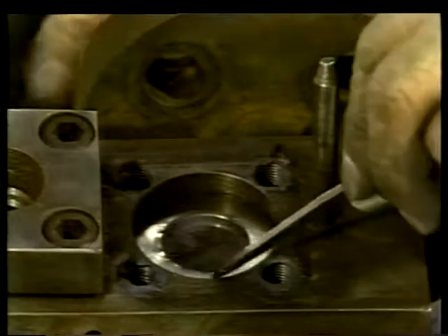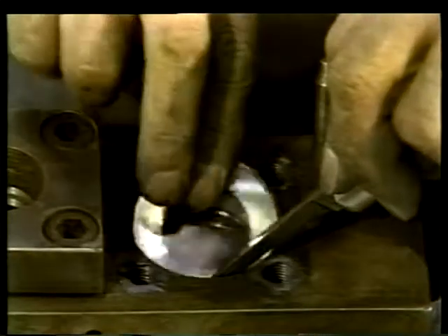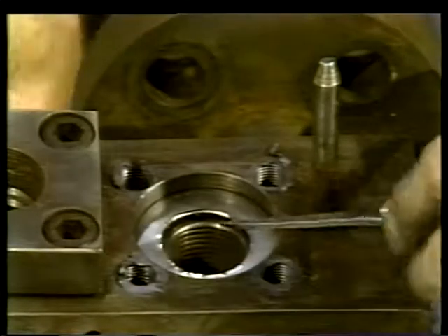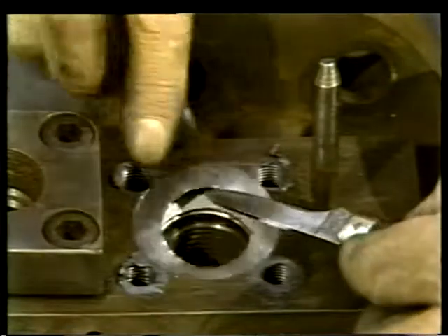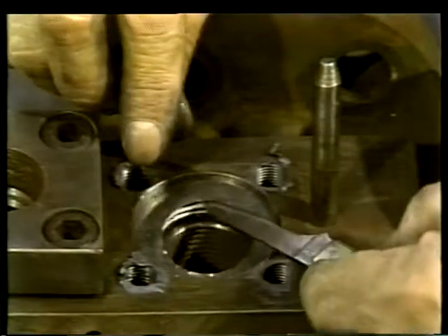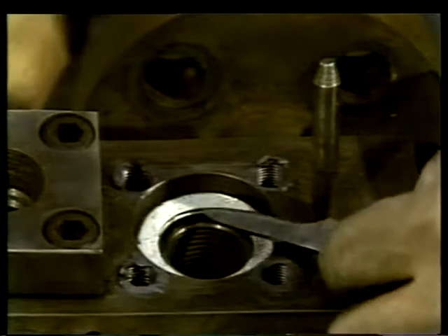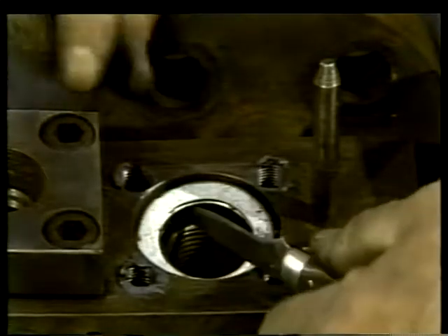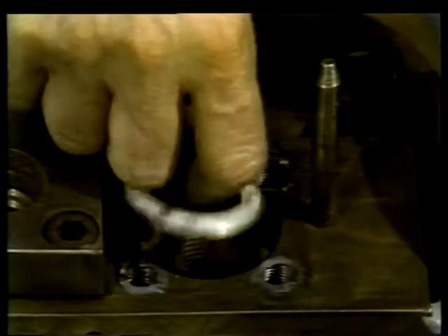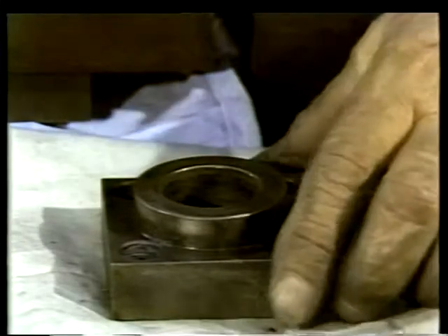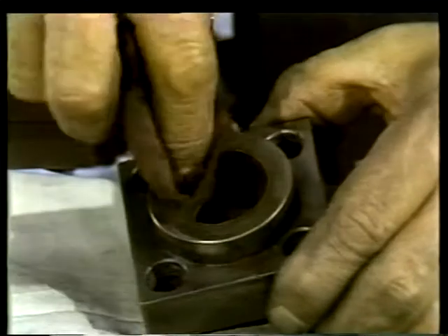Next, take the mica out of the body of the gauge. This mica cannot be reused. Remove the protective gasket found just underneath the mica. And then the sealing gasket, found at the bottom of the gauge port. Finally, clean and inspect all the parts.